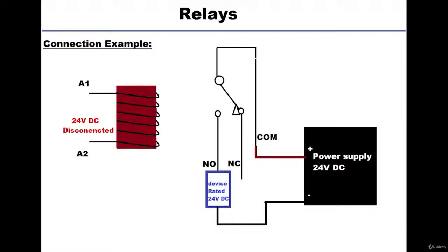However, if the device is connected to the NC, then without energizing the coil, the device will be operating. And once we energize the coil, the device will not be operating. So connecting the load to NC will reverse this operation.